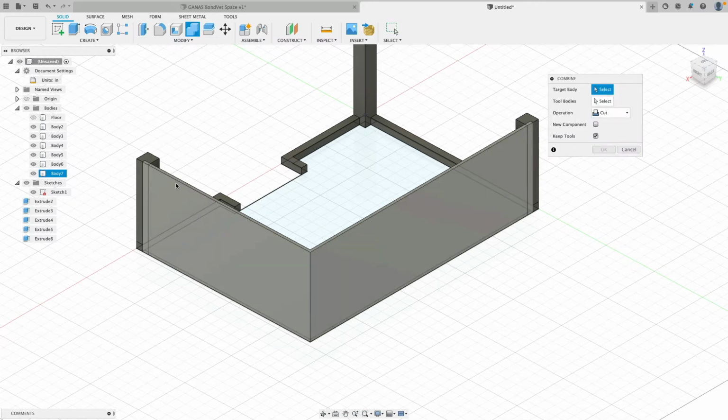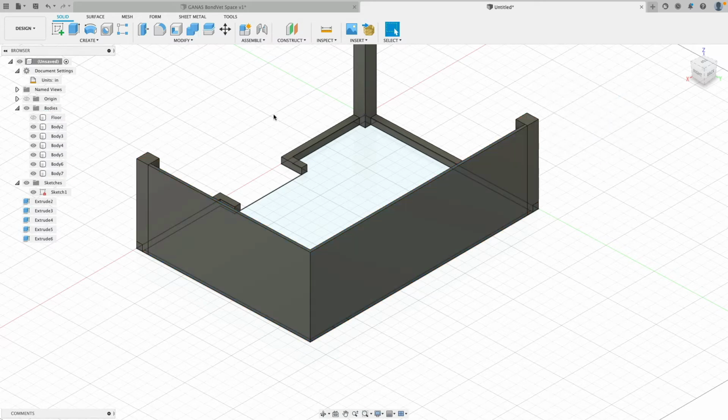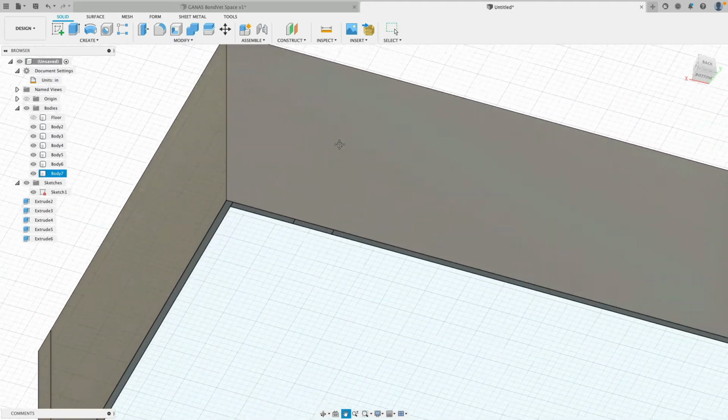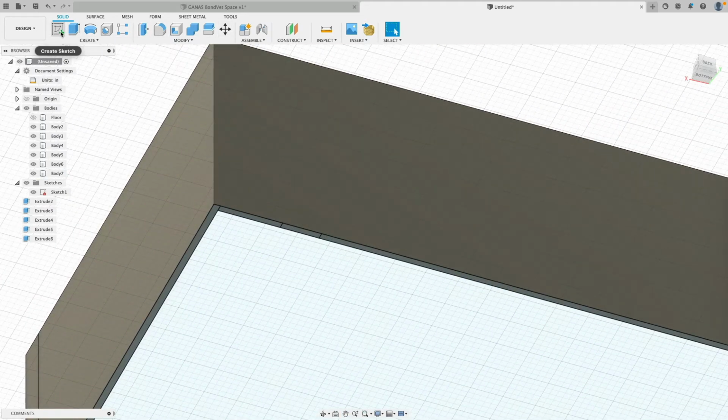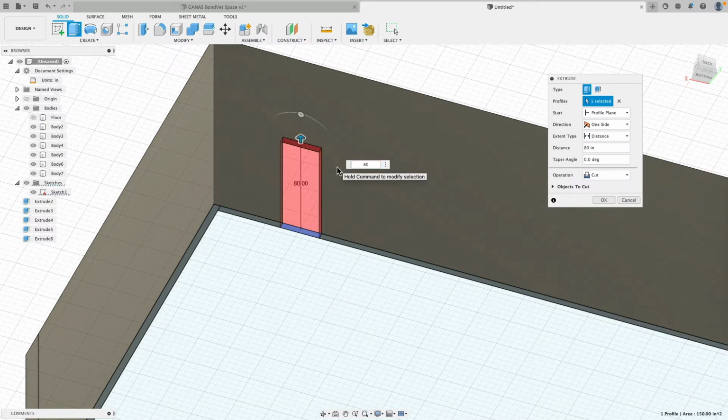Now, as you can see, this wall intersects with these posts. Okay, so we say U minus this one and this one. Keep the tool, very good. Now the interior walls are trimmed. We also have here an opening. Okay, so extrude this one up by 80 inches.